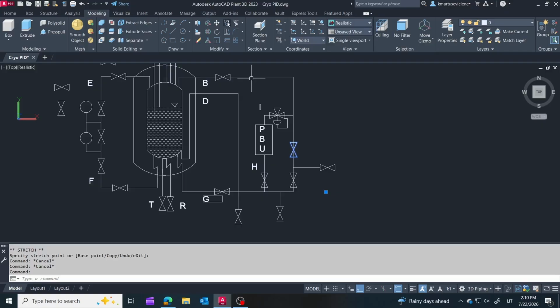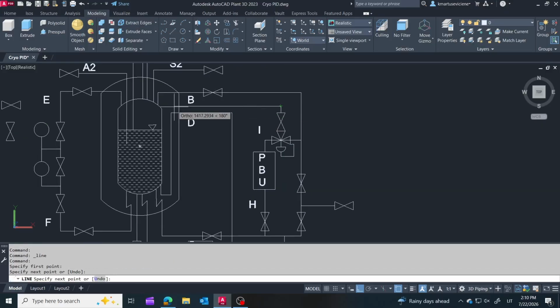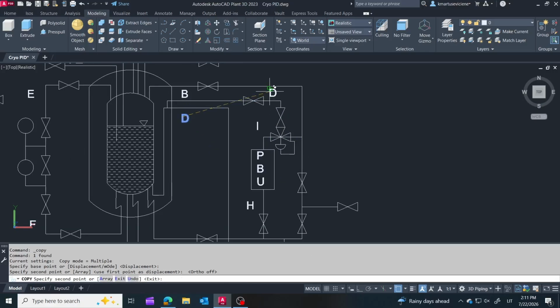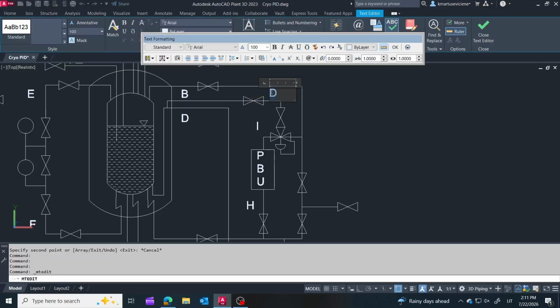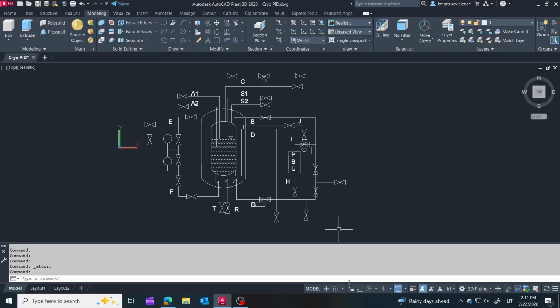Next, I'm adding the Economizer line. As liquid nitrogen is stored, a small amount naturally boils off, increasing the pressure inside the tank. Instead of venting this gas to the atmosphere, the Economizer circuit makes use of it. When the tank pressure rises above the Economizer set point, gaseous nitrogen is supplied to the process first. This reduces unnecessary liquid consumption and helps bring the tank pressure back to its normal operating range. Once the pressure decreases, the system automatically returns to its normal operating mode.